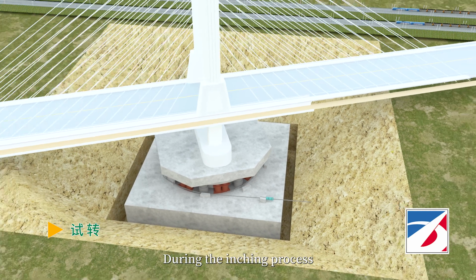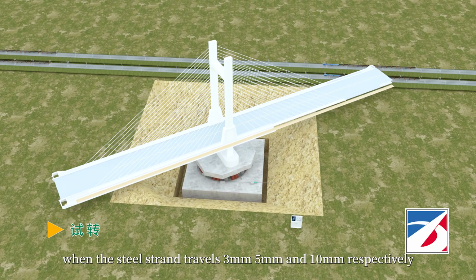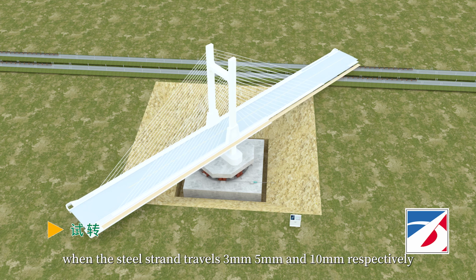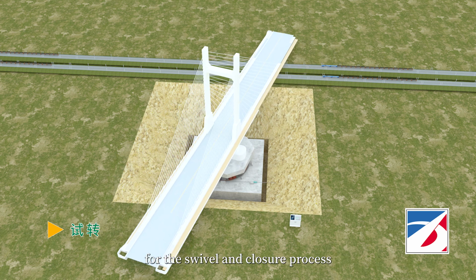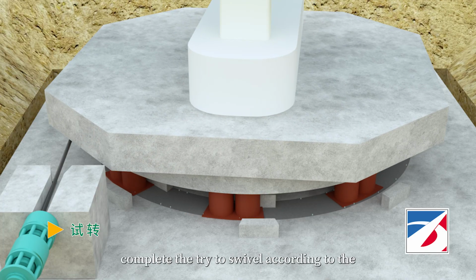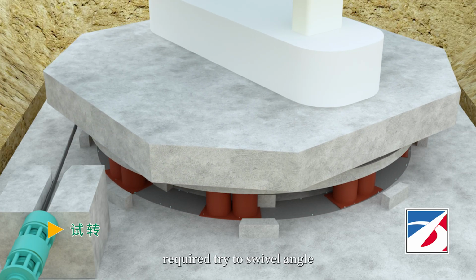During the inching process, record the corresponding travel of the beam end when the steel strand travels 3 mm, 5 mm, and 10 mm respectively. This provides effective data for the swivel and closure process. After data collection is complete, complete the trial swivel according to the required trial swivel procedure.